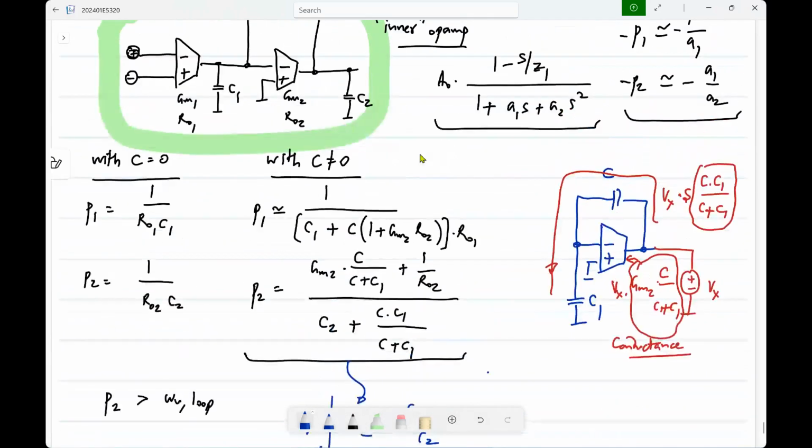So again, I won't go into how we derived all this, these things you have done earlier, right? But it's basically saying the same thing that if you take this new picture where you're doing this current to voltage conversion using the second stage using GM2, then that op-amp has to have a unity loop gain frequency beyond the unity loop gain frequency that you're trying to realize.